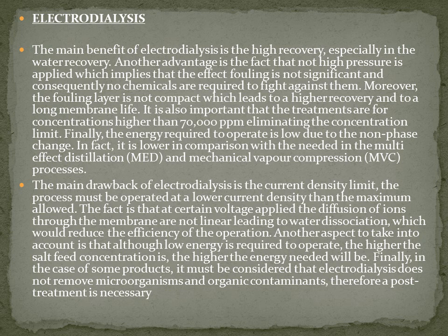The main benefit of electrodialysis is high recovery and water recovery. Another advantage is that high pressure is not required, which implies that fouling is not significant, and consequently no chemicals are required to fight against it. The fouling layer is not compact, which leads to higher recovery and a long membrane life. It is also important that it can treat concentrations higher than 70,000 ppm, eliminating the concentration limit.